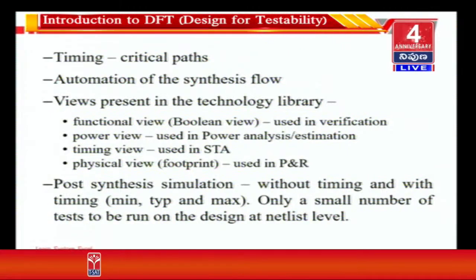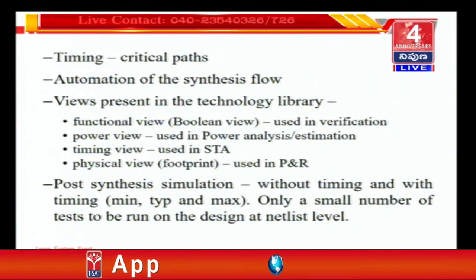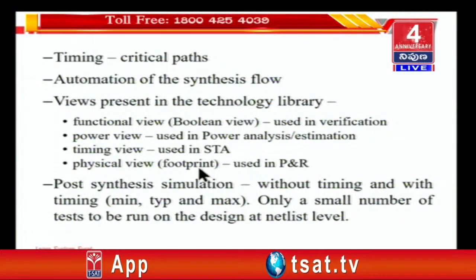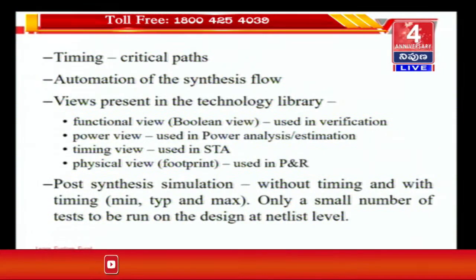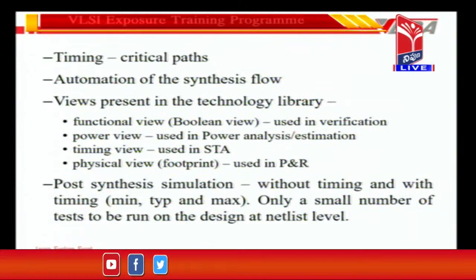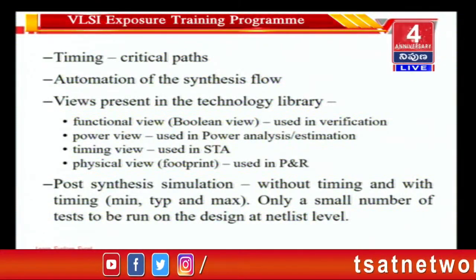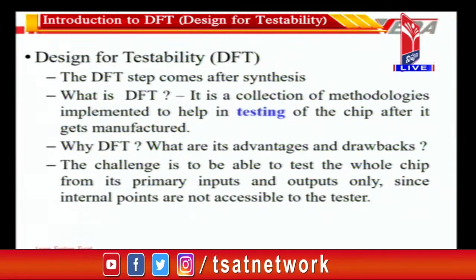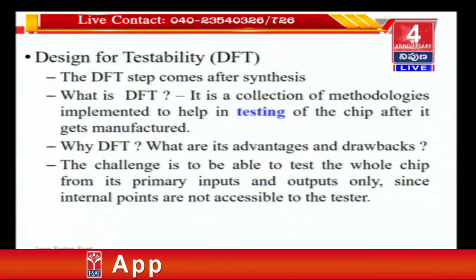That is a netlist, which is a software representation of the circuit that is going to get manufactured, or at least a sub block, if not the whole block, if not the whole chip, at least the sub block part of it. Okay. So now let's go to the next. At this stage, I will introduce you to the topic of design for testability. What is design for testability?